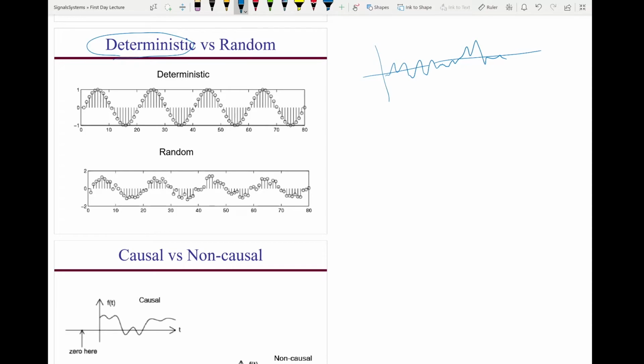But sometimes we say statistical deterministic. That means it's not perfectly periodic, but there is a pattern so that I can predict what the signal will be. Like in speech, when you say the vowel O, E, this looks periodic. And statistically, I can, with some accuracy, predict what the signal will be in the next 1 millisecond, 2 milliseconds. A random signal is a signal you cannot tell. If you watch the signal for 10 minutes, you cannot predict what the future samples will be. Then it's a random signal.